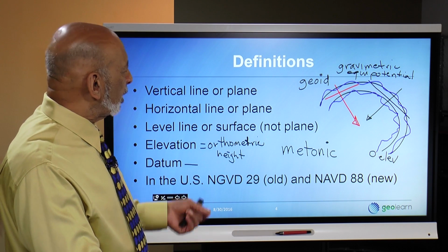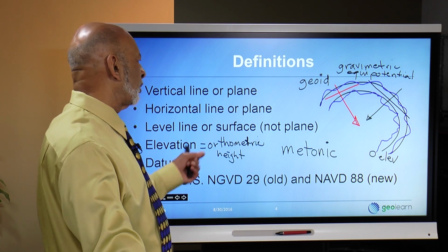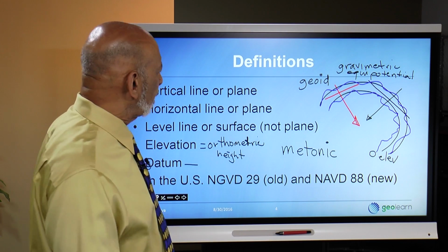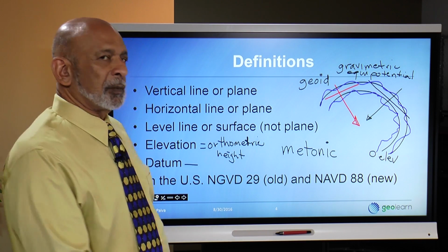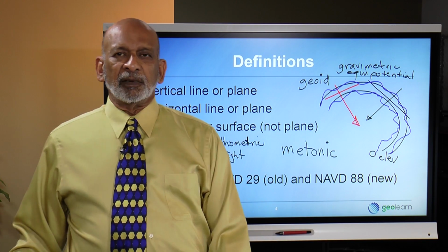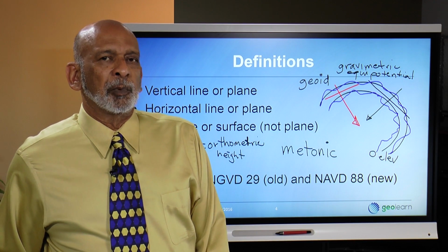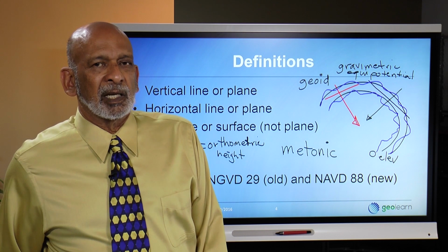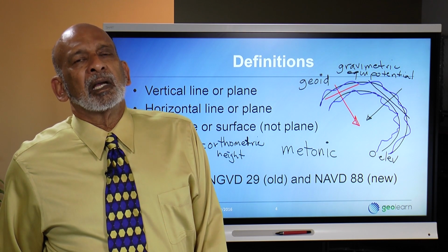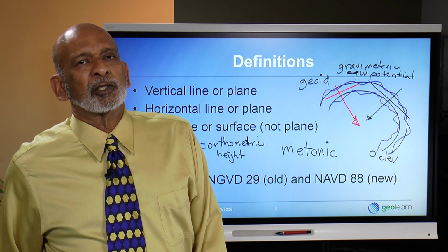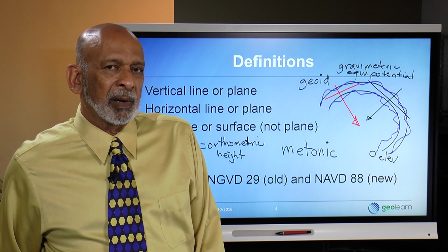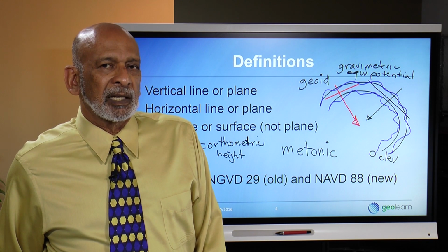The NAVD, which is North American Vertical Datum, and I'm fairly sure that's shared with Canada, of 88, they simply said, you know, what's the elevation using the old datum at this point? And they came up with a number, and they said, well, let's call it that here, and then we'll refer everything else to this one point and forget about trying to average sea levels.